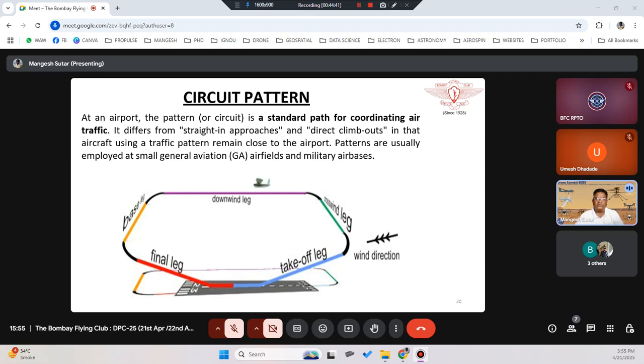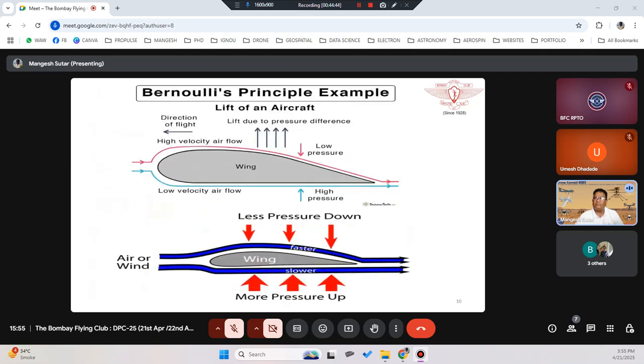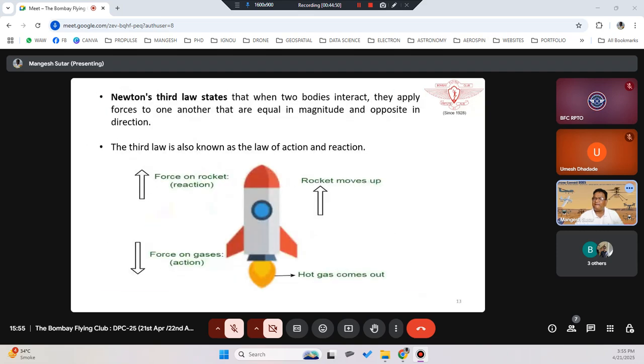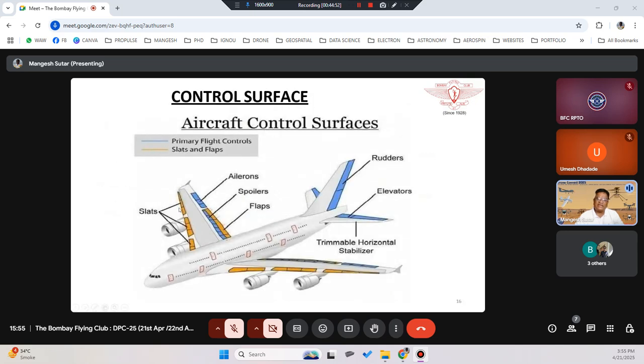Okay, there are additional control surfaces like I was talking about earlier. There are additionals like slats, spoilers, flaps, then you have rudders, which also come as primary rudder and secondary rudder. They are nothing but a combination of extra control surfaces. For example, what flaps do is they extend and enlarge the shape of your wing. So the more wing surface you have, the better lift you get. But once you are airborne, you do not need such a large surface, because then you just have to maintain the flight level.